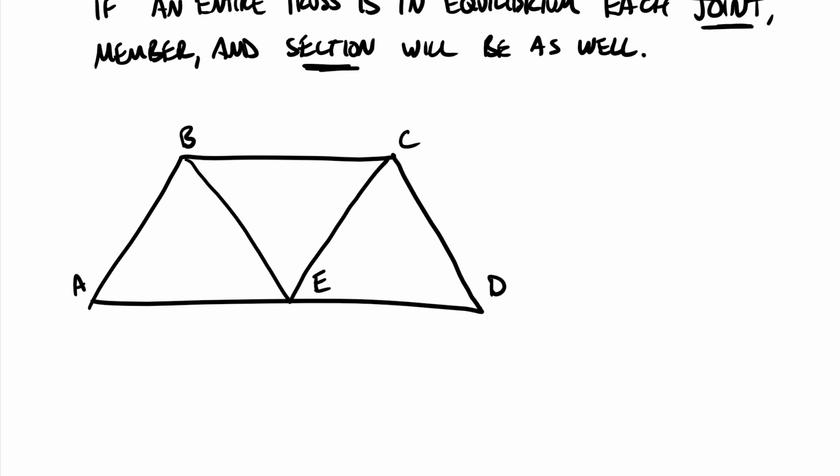It just gives you some reference points. And this is going to be a bit of a cantilever truss. Let's say we're going to put a pin here right in the middle. A pin is a free rotating pivot. So this will be EY, EX, and a vertical force over here, AY at point A. So 3 external reactions, 1 applied force.